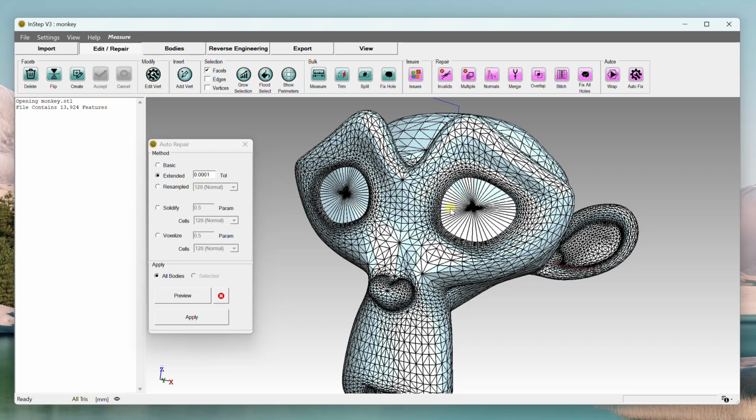And in this case the valid solution that it applied was the hole fixing tool. Now once you've done one or the other of these, you're getting into these three options, and these can be very slow to process. So I always recommend that if you try one of these, start with a small value just to see what it can do.